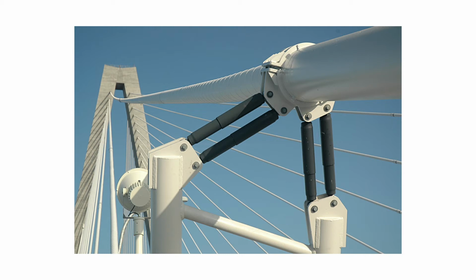I've shown you pictures of buildings so far. What you should know is that dampers are not unique to buildings. They are installed on bridges too. These dampers shown here are installed for each of the cables in the Arthur Ravenel Jr. Bridge in South Carolina. These dampers absorb some of the kinetic energy from wind or load-induced vibrations on this bridge. This bridge was designed to resist large earthquakes, and these dampers might have to do something with that as well, I wonder. And also, you heard me right, South Carolina is pretty earthquake prone.